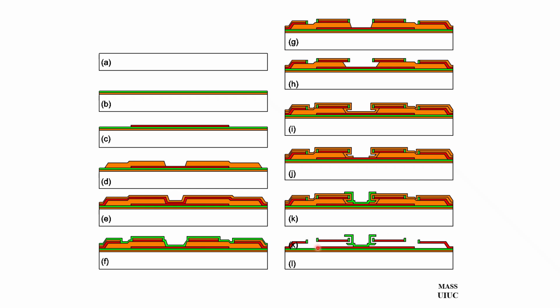After you remove all the sacrificial layer, then you have a very delicate structure with features that prevent the rotor from falling to the substrate and getting stuck. And you have silicon nitride bushing that reduces the friction. This obviously takes the most time and is the most advanced technology.